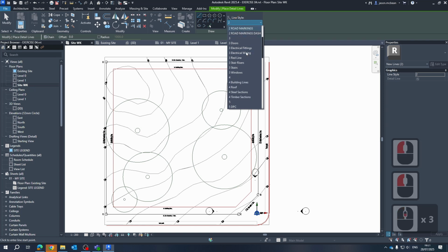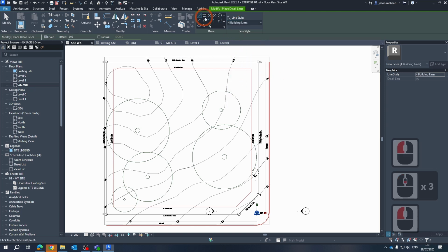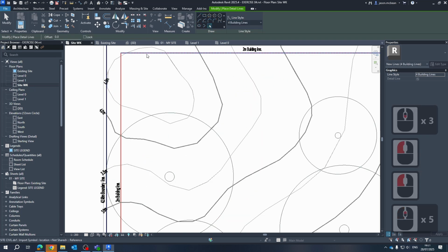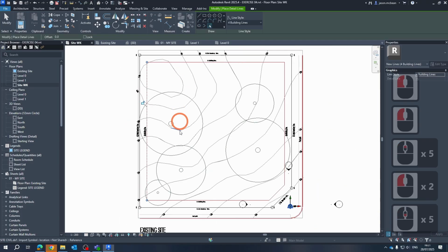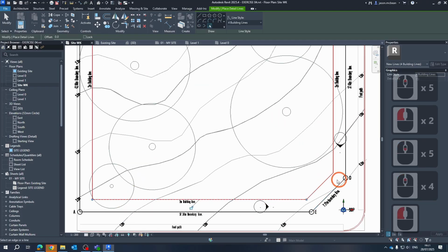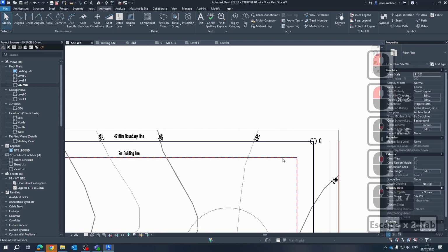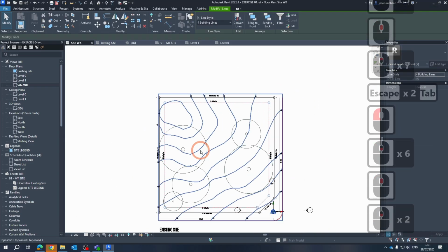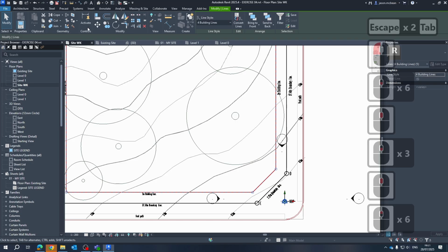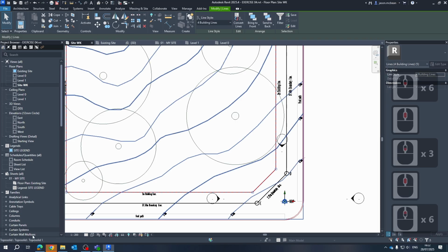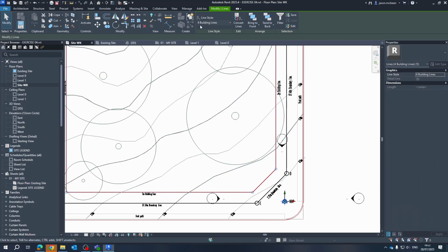The line work is already built in, so for the building line, I'm going to use the pick line tool, and I'm going to simply pick this line, this line here, there, and there. Good. If I tab once or twice, it'll find all this connecting line work. So I can now simply copy this line work, and it'll tell me here at the bottom what it's selecting.